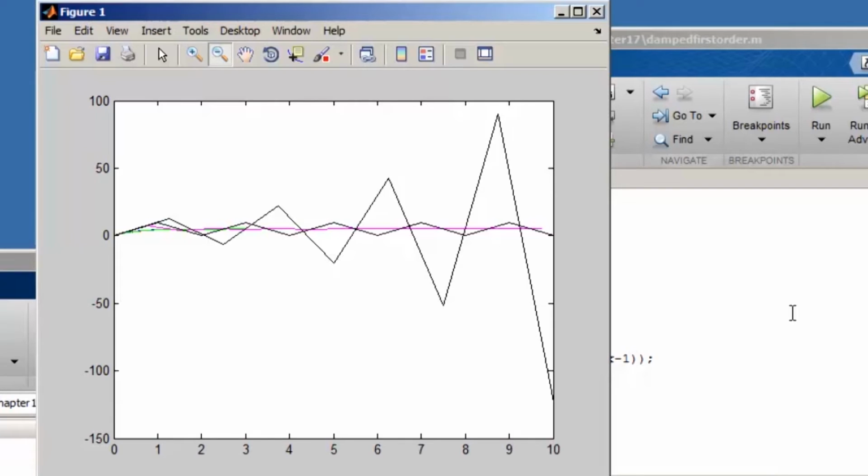Increasing the time step size even more typically causes the oscillations to grow at a faster rate. So, for Euler's method anyway, smaller time steps make the solution more accurate, and increasing the time step excessively can result in oscillatory and unstable responses. This is a typical trend, but it's not at all universal. Different solution approaches have different characteristics, but the mathematics associated with describing them is beyond what we want to do in this class.